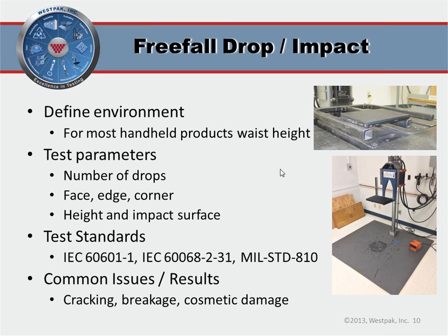If you have a smartphone and you've dropped it, I know I've dropped mine, the corners are what get beat up the most. Usually when you drop something, that's where it's going to land, a corner or an edge. It's very uncommon you'll drop a consumer product and hit it directly on a face. You also need to specify the height. As I mentioned, 1 meter is very typical, but it may be different for your product.